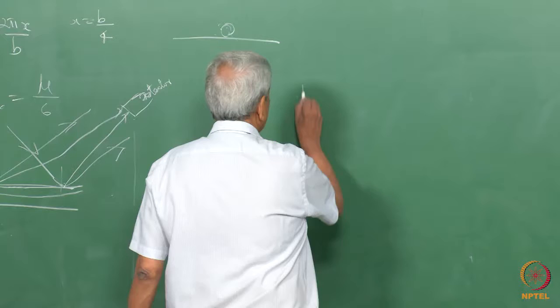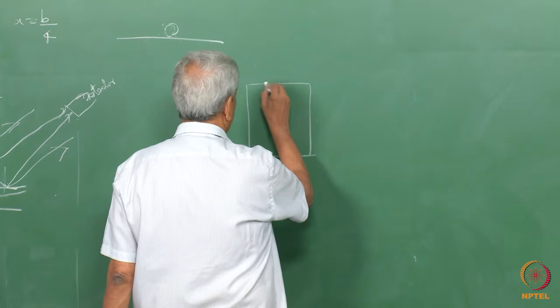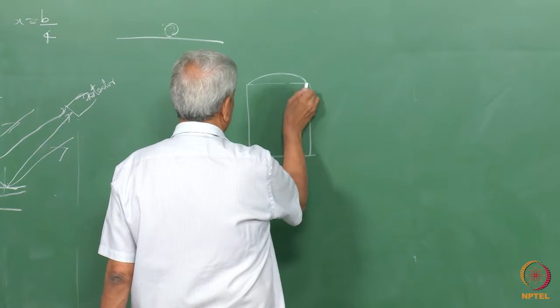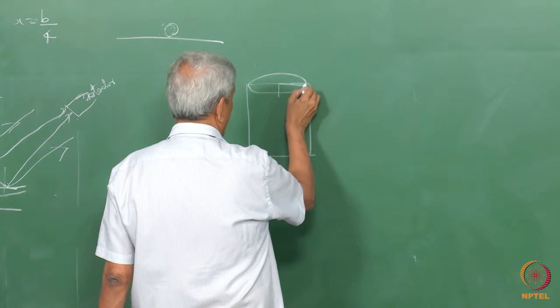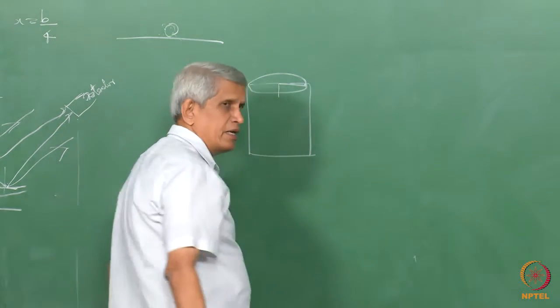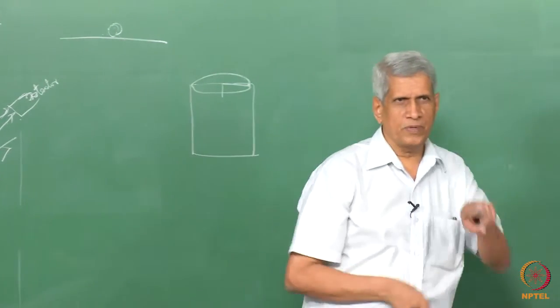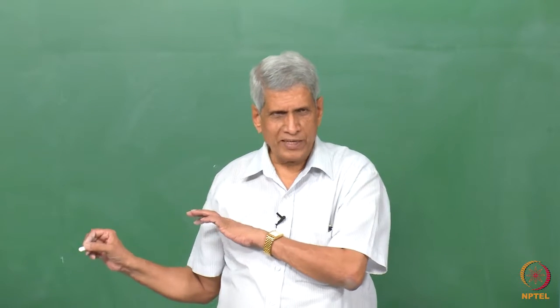If a crystal is growing, you assume that in this direction we are looking at this surface. If a screw dislocation is present, from here to here, when you take one round, there is always going to be a ledge present, one step. This I will come to later.